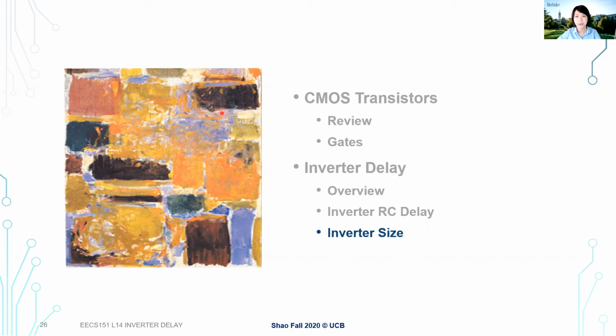In today's lecture, we had a quick review of how the CMOS transistor works. Again, 3 regions, very, very simple. Less than the threshold voltage, 0, nothing going on. Greater than threshold voltage, basically just a resistor, linear function. But then if your drain voltage is too high, it becomes saturated, so you get this flat region. So that's basically the 3 modes of our transistors.